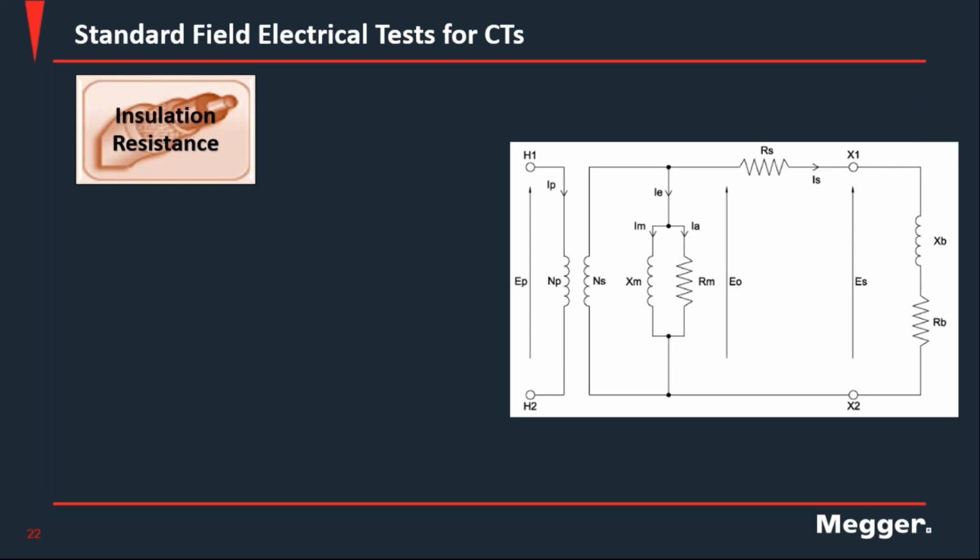Well, the Rogowski coil CT is a little bit different, because the Rogowski coil operates on a differential principle. What that means is that for a current input on the primary of the coil, you're going to have a voltage on the secondary, which represents the current that goes on the primary. The point here is that unlike in a regular inductive transformer, where a current on the primary is transformed into the current in the secondary by basically the turns ratio, if we neglect the losses.